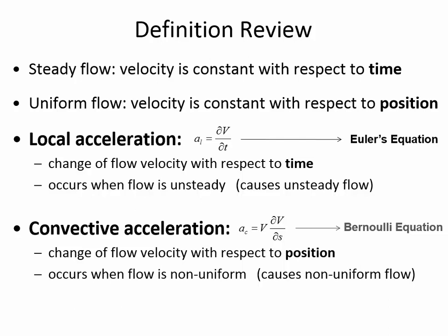So what if this tank, instead of being held steady, was being accelerated to the right? What if we set it onto that rocket sled that we saw the video of today? Would the pressure at 1 versus the pressure at 2 only depend on the elevation? No, it would depend on how quickly that tank is being accelerated. So that's an example of how acceleration is going to change the pressure-elevation relationship in a way that the hydrostatic equation can't address. So we're going to spend a couple of class lectures going over these.